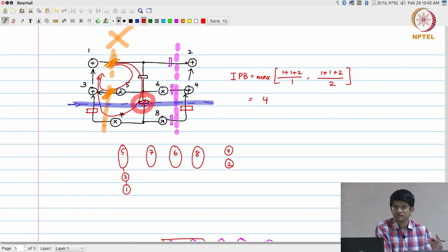In other words, they have complete mobility. They can be scheduled in any one of steps 0, 1 or 2. Okay, that's the problem. They can be scheduled in step 0, 1 or 2. I need to think one step further and see which one of them can go into 3. Okay, so even though I am trying to do this systematically, the fact that there is a pipelining step over here, or rather the fact that there is a spillover from one iteration to the next, I still need to take care of that a bit more carefully.